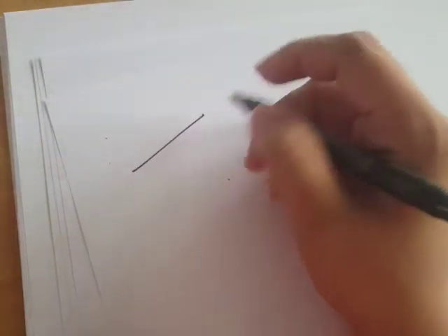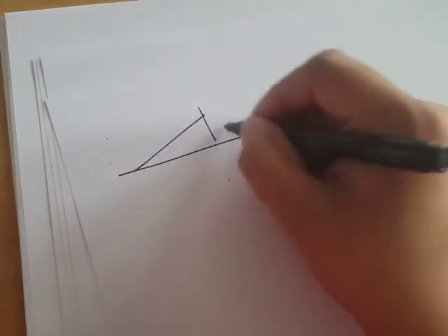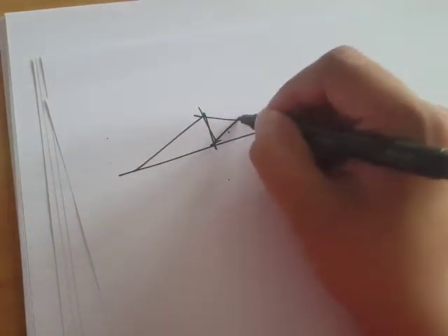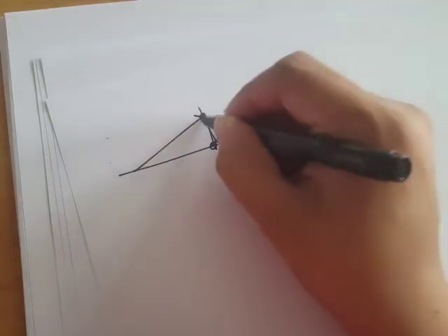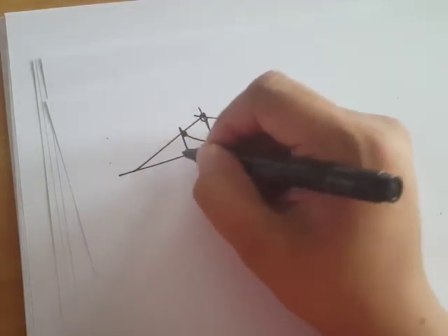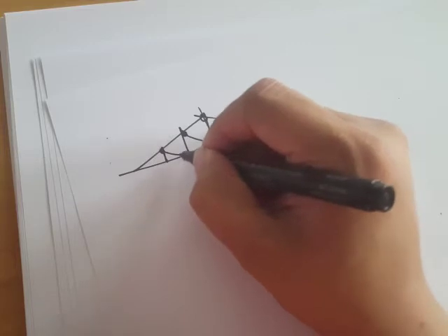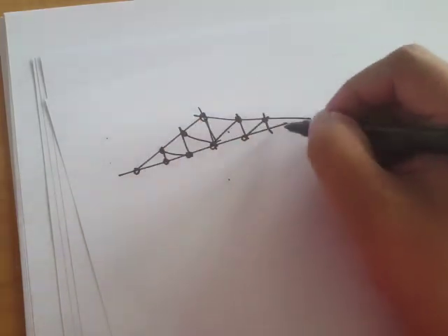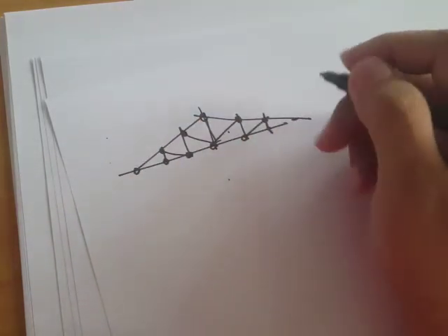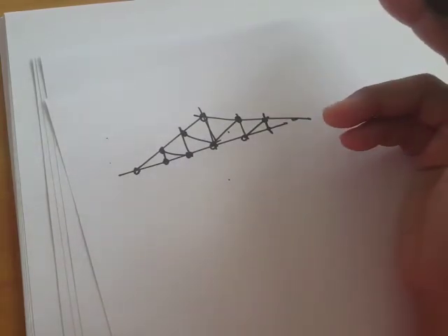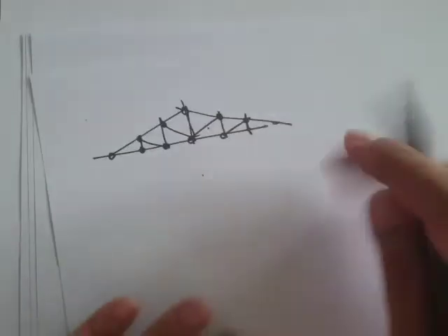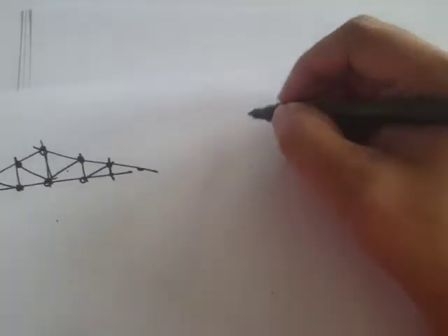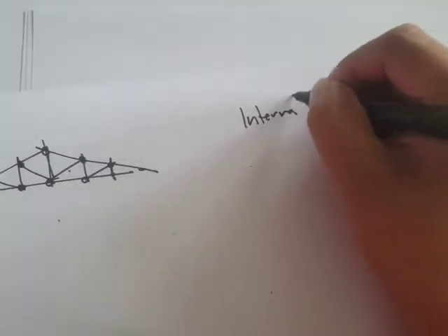Like for example, the trusses that I mentioned in the previous video. The joints of the truss, we said that it's welded, right? It's welded, but in analysis, we just assume that it's something like a pin support, and that's actually internal releases. Okay, so I think we'll discuss also the internal releases.